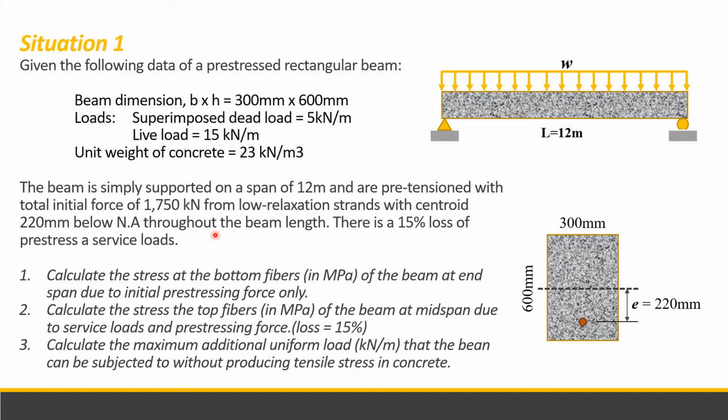So meaning the resultant stress given the loading and the pre-stressing force at the bottom fiber is 0, no tensile.